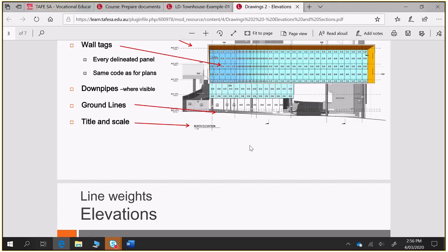So in our elevations, do we have a line that follows the contour, or is it always just like... What you're doing a building pad and you're doing retaining walls around it, so don't show any contour of the land. So as far as the building elevations, just have a flat line. Yeah. What I've done a fair bit in the past is whenever it's important, I'll show something like this. Building pad, land, that's cut and fill information, then show, and I'll show something like that in an elevation. So you can see still the land coming and going from that elevation.